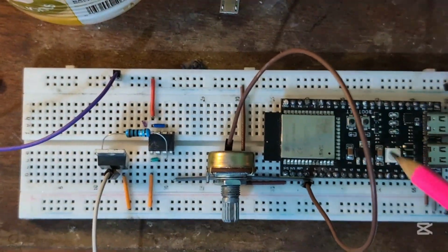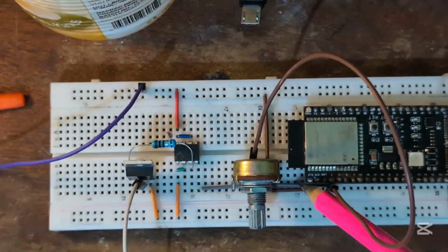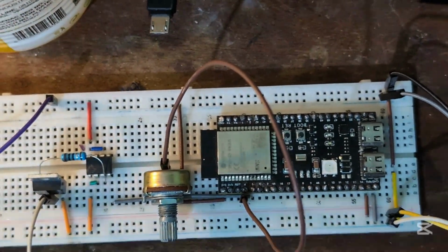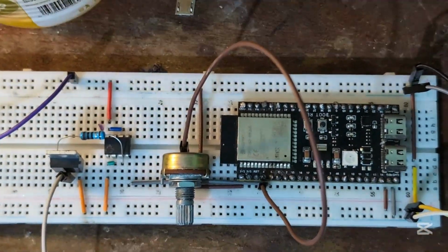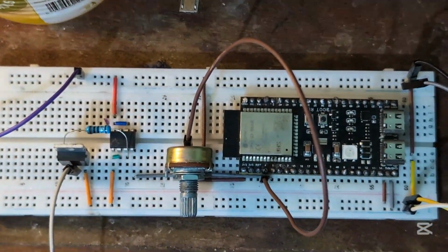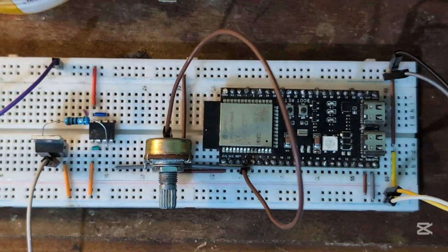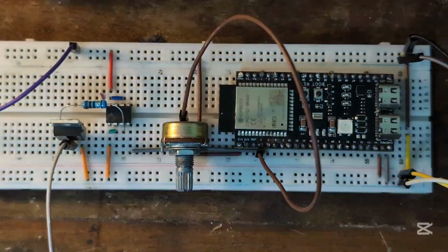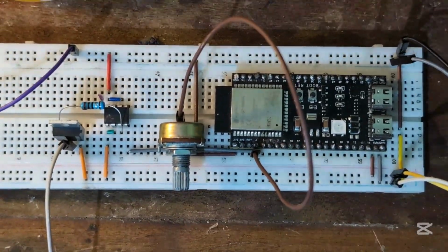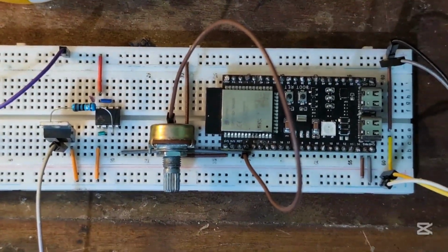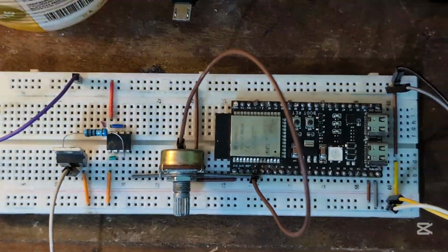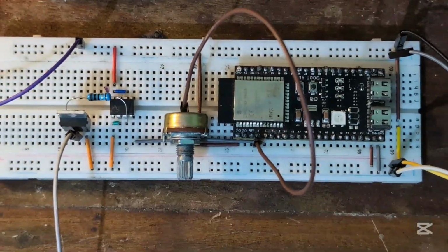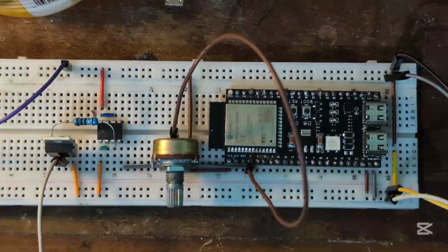Now our signal is coming from the ESP32. So this gray, or the ash, this gray wire moves from pin 5 and goes straight to the reset pin on our NE555. So that's the control signal. And then in my code, I set it to a PWM frequency of 28 kilohertz. That's above ultrasonic speed. One thing to note is that they all have to share a common ground, and one thing about ground is it's always 0 volts. So no matter what the VCC might be, whether 12 volts, 5 volts, 3 volts, or even 300 volts, ground is still 0, so they can all share a common ground.